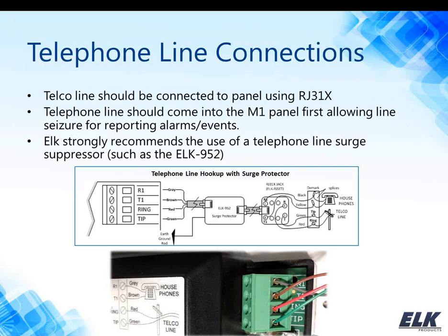You do need at least 6 foot of wire between that surge protector and the M1 panel itself, so it has time to clamp down on that surge that may be running across the telephone line itself.